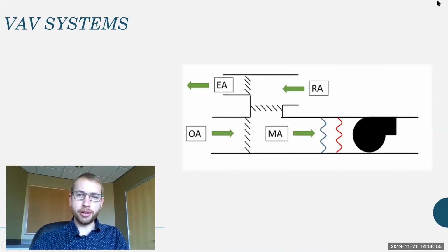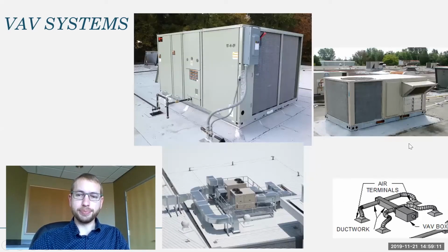Looking back at our diagram, we've got outdoor air coming in. We're going to cool that air down to 55 degrees, regardless of what the outdoor and return air conditions are going to be. And then at the terminal unit, we'll probably heat that back up again. And we'll do that for each zone, depending on the heating or cooling needs within the space.